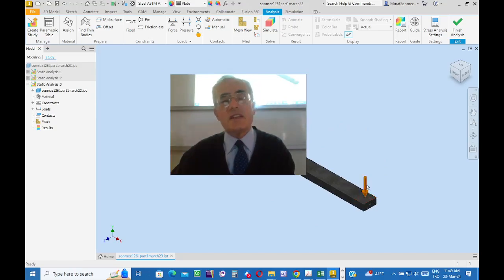And now with such a laterally directed load, you know, the famous name, it is a cantilever beam. At this end, it has been fixed connected. It is like a beam. Whenever a bar or prism is loaded laterally, then we say, okay, it is a beam. In the jargon of civil engineers, it is called a beam. If its end is fixedly connected, then it is called a cantilever beam. Maximum deflection will be at the free end. Minimum deflection here, but the maximum stress is going to be in the vicinity of this fixed connection.